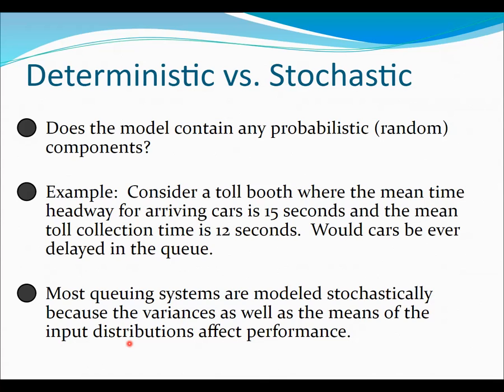And this makes sense because our traffic flows work like that. We don't exactly get the same thing every day. That's why a good practice when you're doing the simulation is that you always run the model at multiple seed numbers, and then you average the performance measures across those seed numbers.